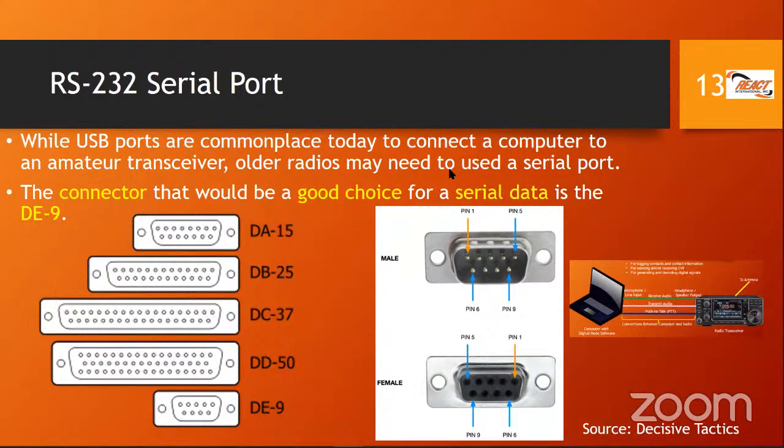USB is very popular today, but we still need to learn about the serial port, which was very common many years ago. You almost always had a serial port on a computer. Nowadays, you may hardly find one; you may find a USB to serial port dongle. But slightly older computers will have them, and we can still use them. Some will say the serial port has really not gone anywhere, so we need to still be familiar with it. This is what it looks like, the male and the female. Sometimes one is called DTE and the other DCE, data terminal and data communication equipment. So these are physically what they look like.